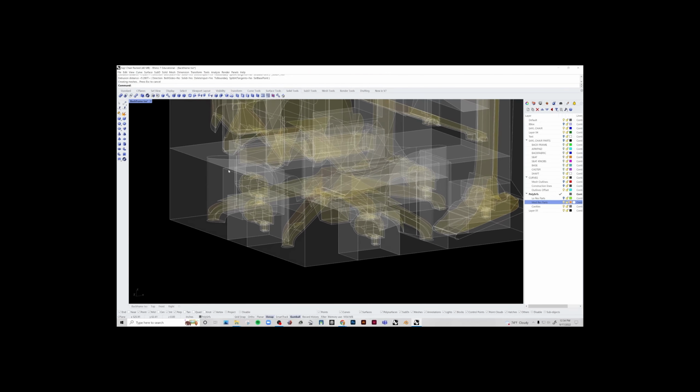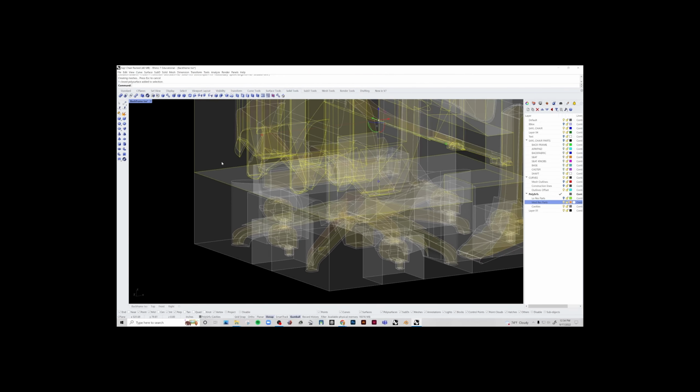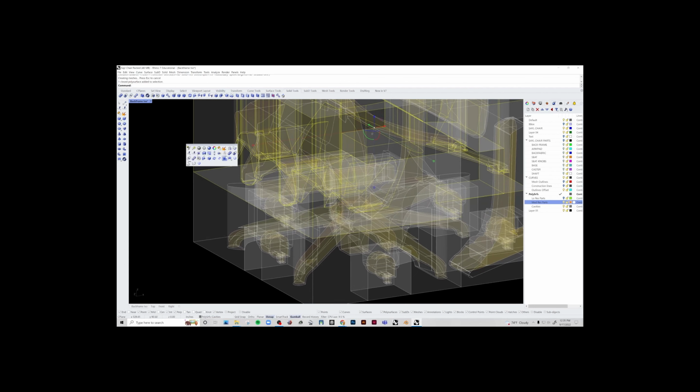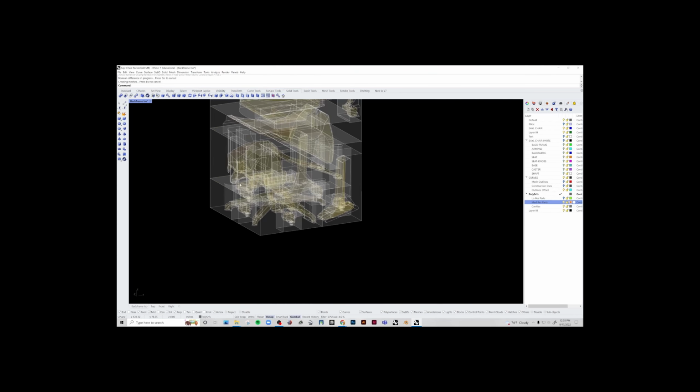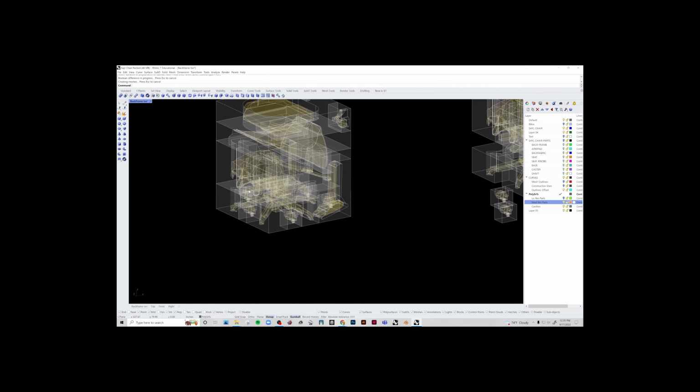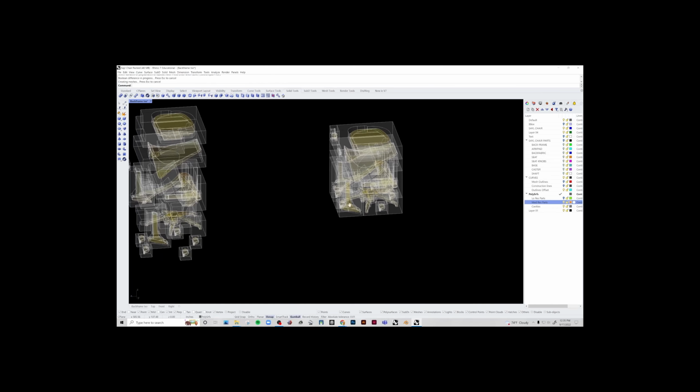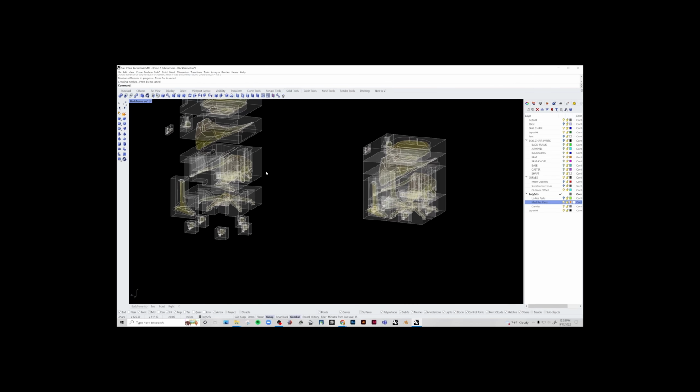Take it to there. There's a setting that you can change when we do Boolean difference or any of these. So right now I have it set to not delete the input. But if I click yes, then as soon as I do that, it will just automatically delete the piece that got differenced out. Okay, so that should be set. So I should be able to replace this.